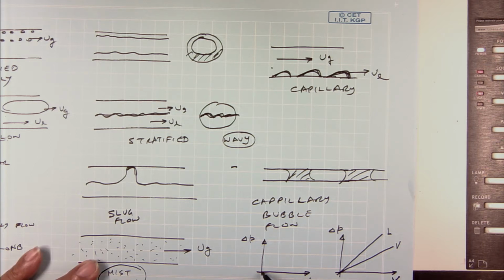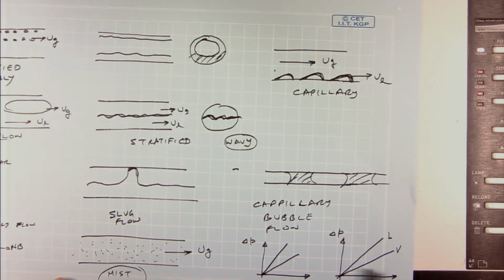Now, I do the same. So, if I were to translate this data and I do the same plot, but now I do it with respect to the mass flow rate, which one is liquid, which one is vapor. What do you think? Or in other words, for the same flow velocity, I will get lower pressure drop for the vapor and higher pressure drop for the liquid, isn't it?